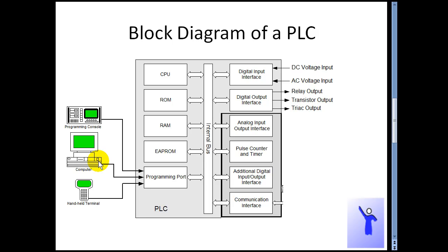There are PLCs which require proprietary connectors. The connectors are non-standard. For them, you will have to contact the manufacturer of the PLC for getting the cable or the converters required to connect the computer with your PLC. And then there are these handheld terminals which you can use to program the PLC. They will be pretty much useful if the PLC is inaccessible or you don't want to carry around a laptop. But nowadays they are increasingly being replaced with small laptops.